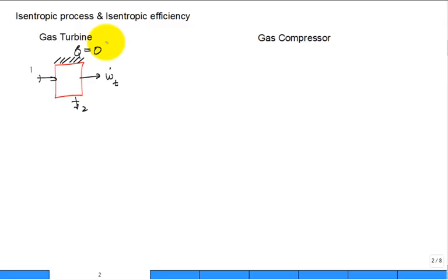So we analyze it by introducing a control volume. And we do a first law analysis for the turbine. From the first law, don't ever forget what the first law gives us. The power out of the turbine is equal to the mass flow rate through the turbine times its inlet minus its outlet enthalpy, neglecting changes in kinetic and potential energy. It's adiabatic, steady state. Do you like that? Yeah. What's the second law look like?